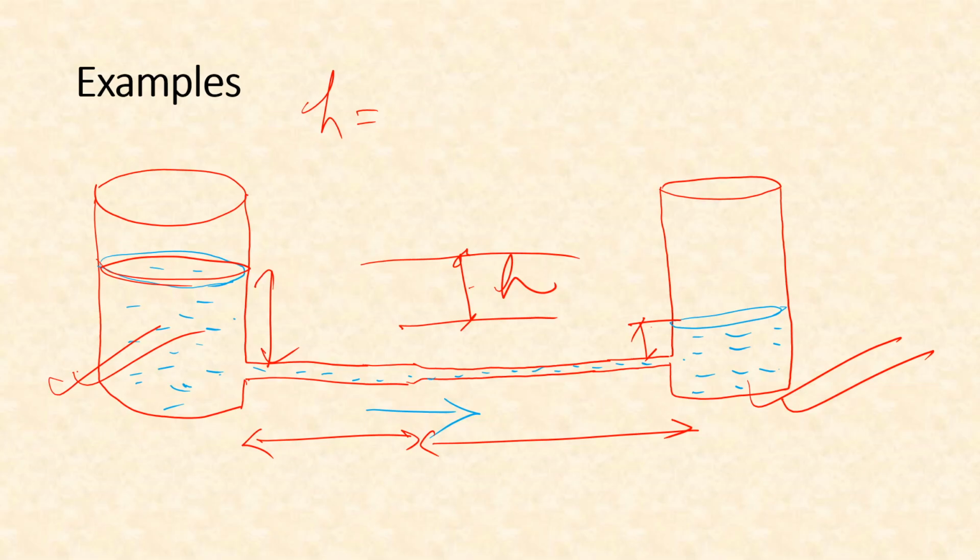For the sake of completeness, you can also add head loss at entry, plus head loss at A, plus head loss at sudden contraction, suppose we call it HC, plus head loss at B, and plus head loss at exit, like this.